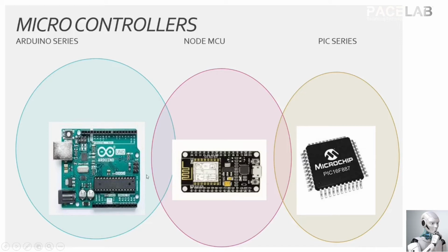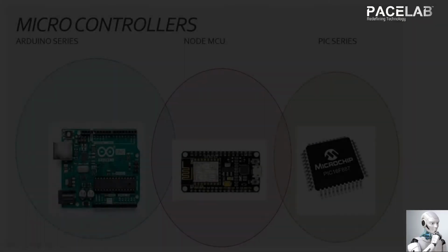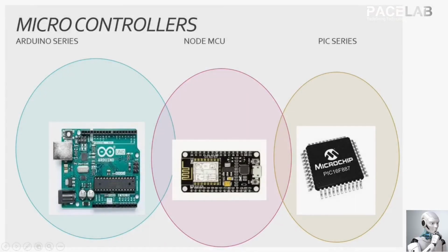The main part, or the main controller, is the microcontroller. The name of that is ATmega328P. And there are analog pins and digital pins and selected PWM pins available in Arduino Uno, which was the first series of Arduino. And there are a 5-volt supply pin and ground, a power supply jack, a programming USB connector, and a crystal oscillator for programming purposes.